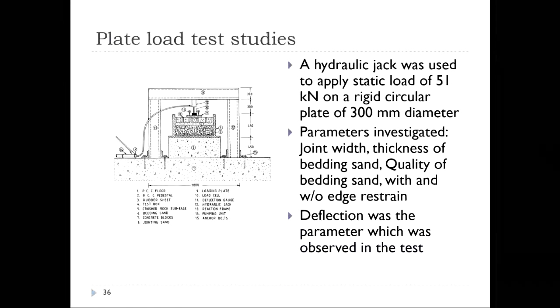Now, this is the loading. A hydraulic jack was used to apply a static loading of 51 kilonewtons on a rigid circular plate of about 300 mm diameter. So this is your conventional plate load test. Using the jack, they were pumping oil and applying this load.